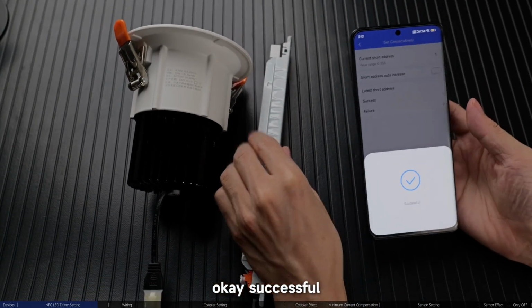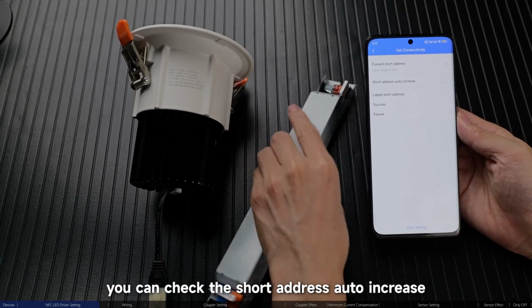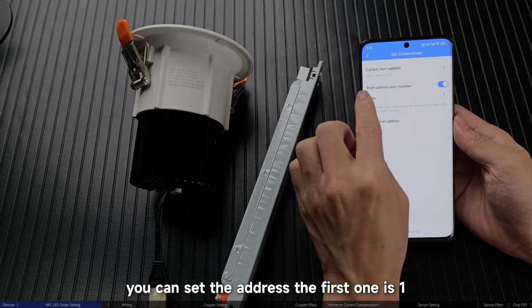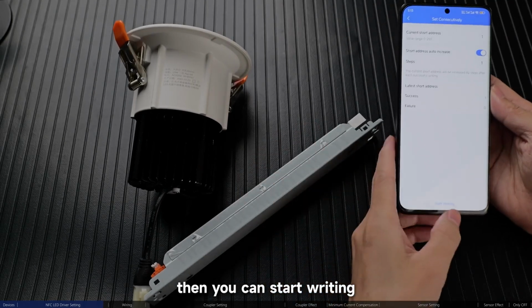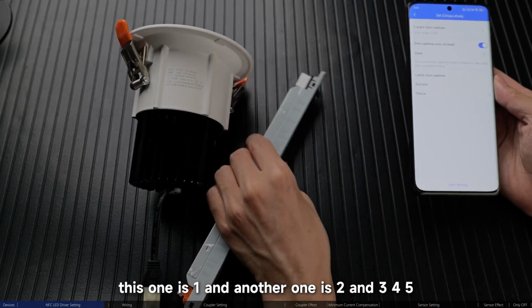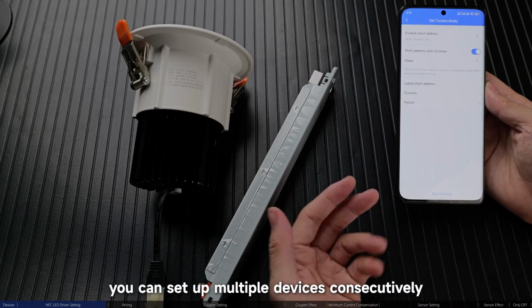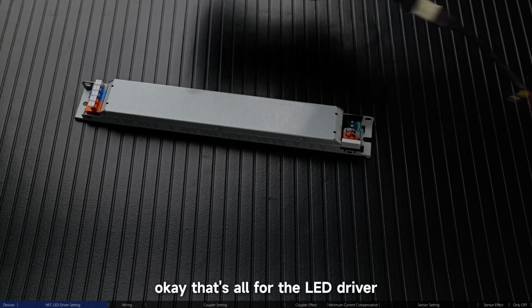Okay, successful. If you have multiple LED drivers, you can check the source address auto increase. Here you can set the address. The first one is 1, then you can start writing. This one is 1 and another one is 2 and 3, 4, 5. You can set up multiple devices consecutively. Okay, that's all for the LED driver.